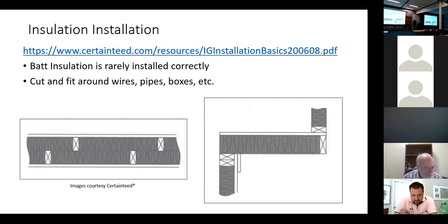The insulation manufacturers for loose fill or batt fiberglass type insulation require that the insulation be in contact with some type of building material or air barrier material on all 6 sides. Now, what do I mean by all 6 sides? If you're looking at a wall: bottom plate, top plate, stud on either side, drywall, sheathing.